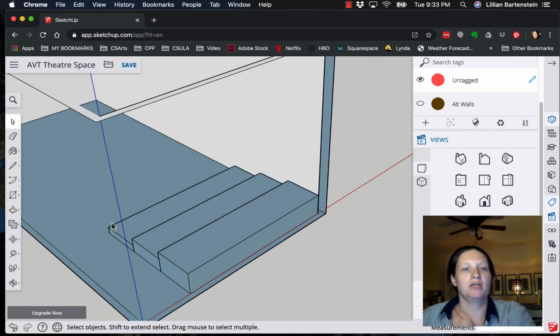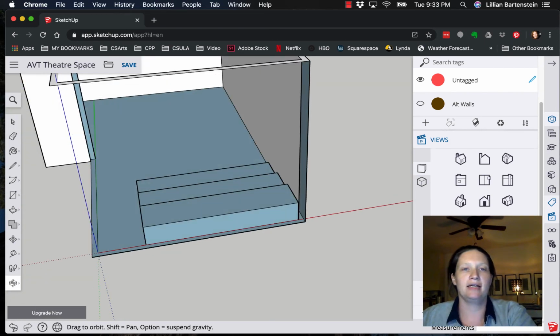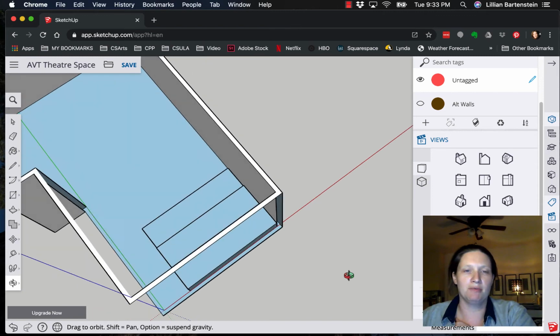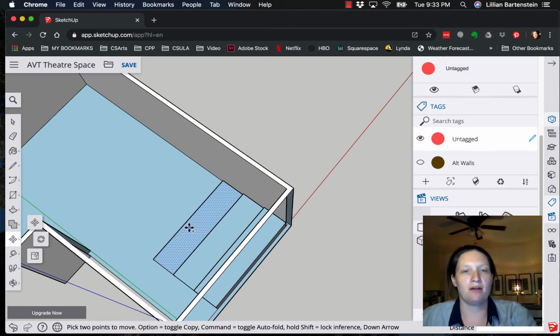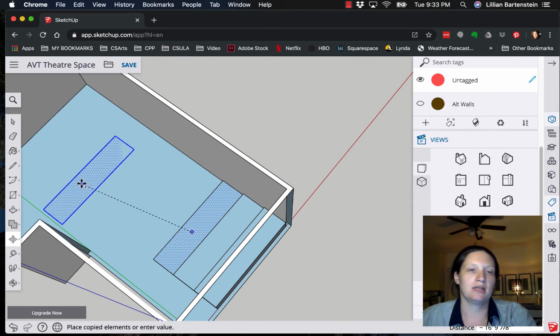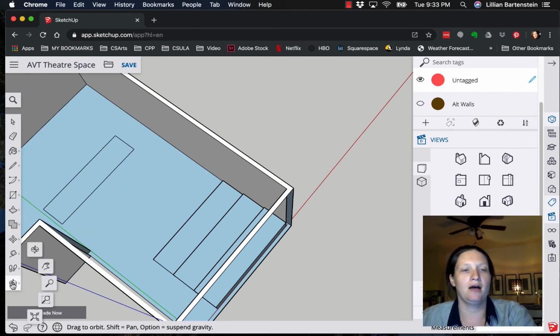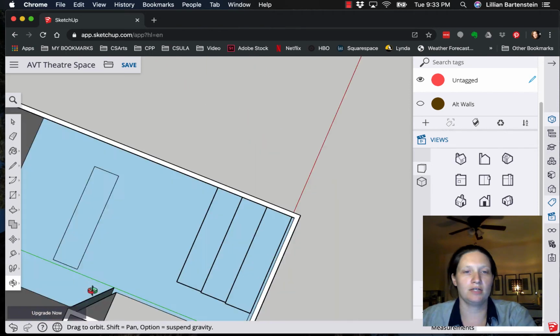I'm going to zoom out a little bit. I want to add another seating riser over here to the side in this corner, because that's actually the other place that chairs are going. So I'm going to grab my lowest riser and copy that once again. I'll pick up the move tool, hold down Option, slide him over here, and now I have another copy of just the rectangle. That's fine.